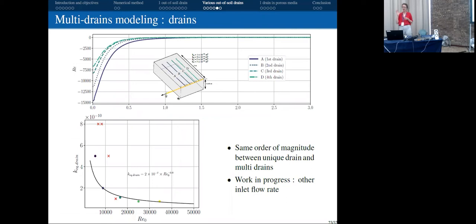I know I have 8 cells in the thickness of the wall drain. It's 2 millimeter thickness divided by 8. Sorry, speak a bit louder. It's 2 millimeter thickness for the wall drain, and I took 8 cells in this thickness. So the entire drain was only 8 cells across or something. That's correct. Okay.